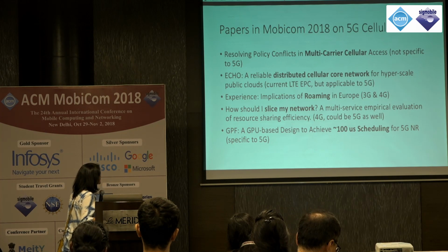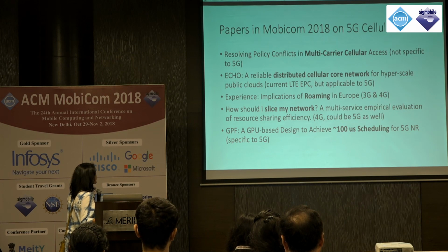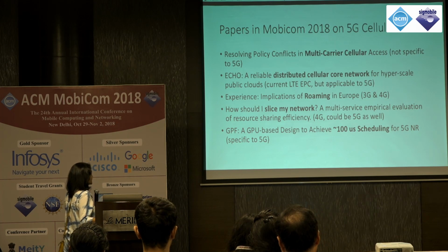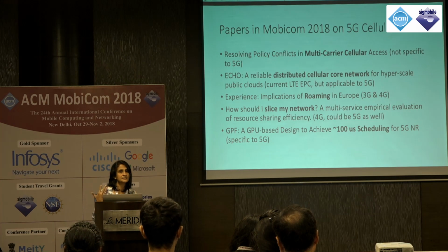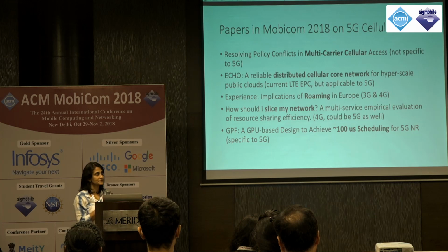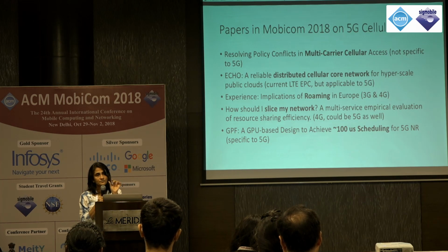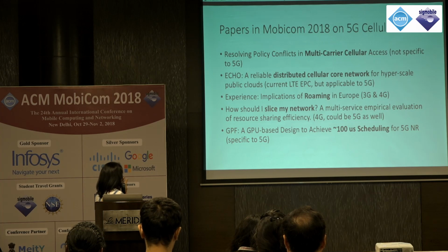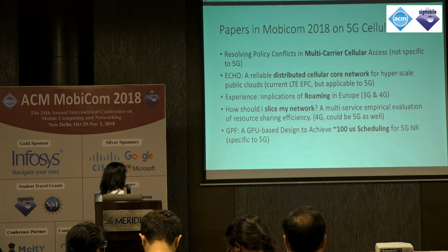And the last paper is probably the one that is the closest and most specific to 5G, because they're really looking at this low latency requirement and looking at the reduced TTI in the specification and asking the question: now that I have this very small transmission time interval, how do I do my scheduling in that little time? They are proposing a GPU-based design to do that, and this is quite specific to 5G NR.